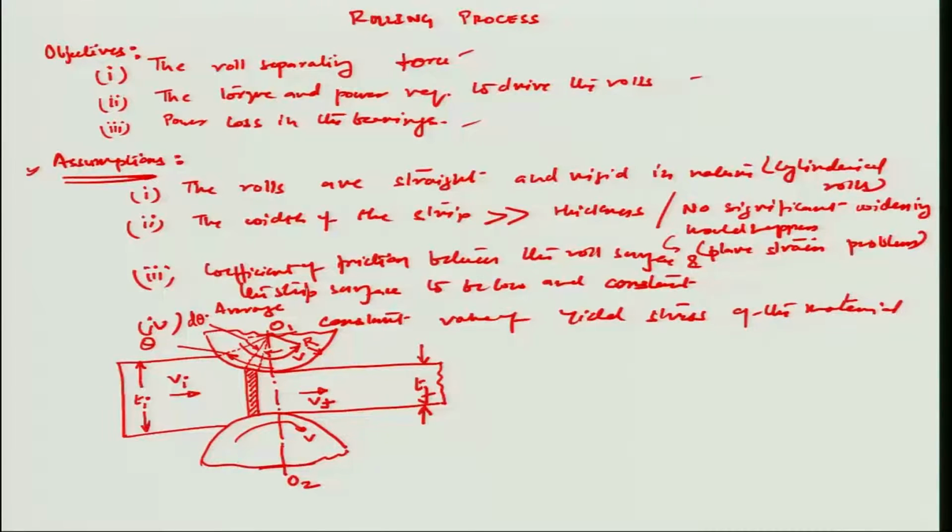Further, I will consider the angle theta to be equal to the initial angle theta i, because that's what the initial angle is at the instant of time t equal to 0 of the rolling process. We are assuming that rolling is already happening, and we will look into such a formulated region right here and try to investigate the balance of forces in this particular region.